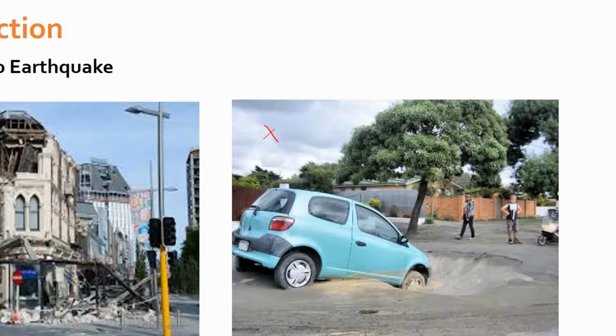How might it happen? If you remember the friction theory, I'll just write the equation in here. Friction force equals a constant K times normal force. That is, if we have two particles, the interparticle friction force between these two particles depends on a friction coefficient that represents how rough these two particles are. And the second thing that controls it is the normal force acting at this plane, the force in this direction.